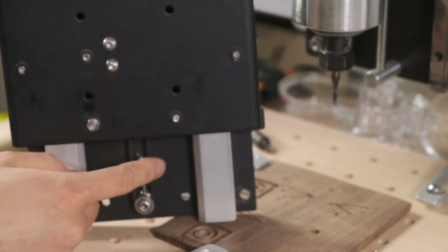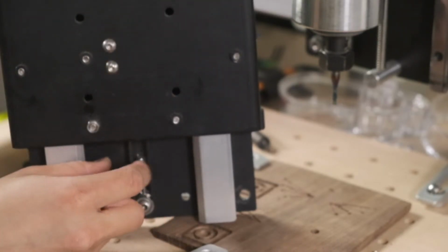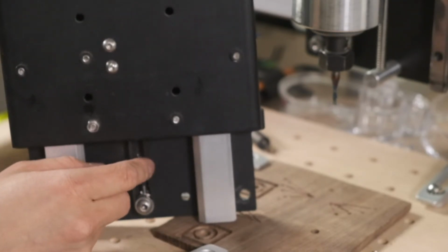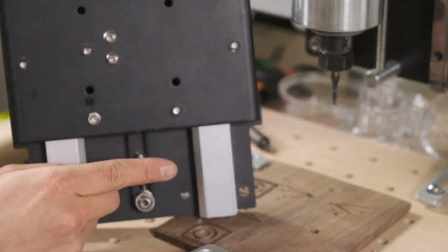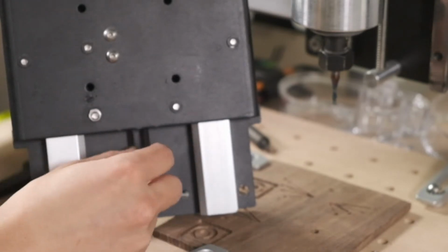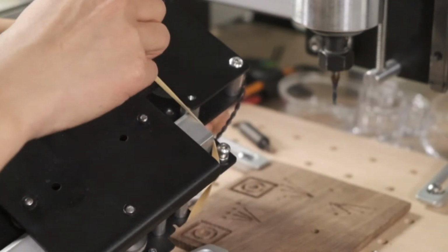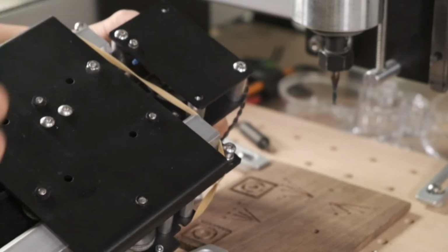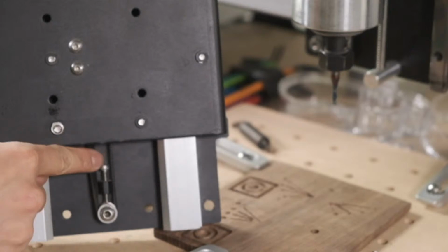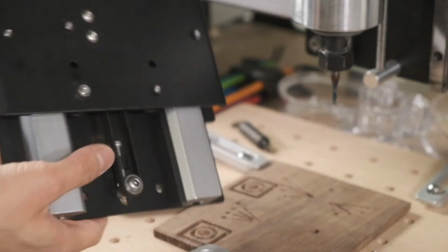This should be more than like a well-done steak. It should be strummable. It's not going to sound as loud or have the same twang as the X and Y belts because those are thicker, but it shouldn't flap around loosely. It should have a good bit of tension, sort of like a very taut, thick rubber band. So that is the tension method for the belt drive. And once you have the right tension, make sure you tighten this bolt and this nut back up.